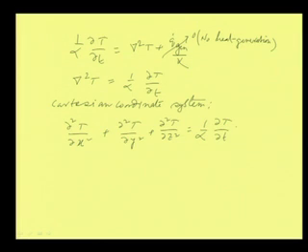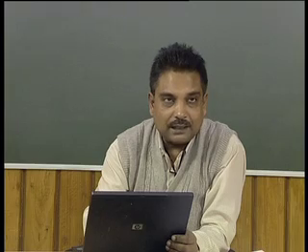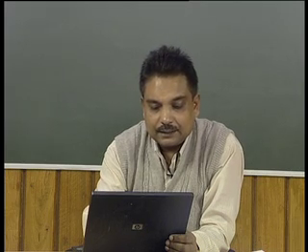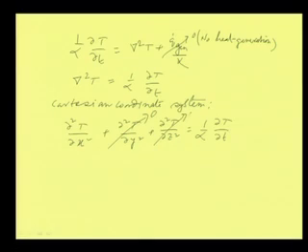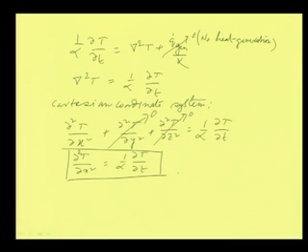We know that this is one dimensional heat transfer. We are not considering multiple dimensions, we are considering only one dimensional heat transfer, and therefore there is no temperature variation along the y and z direction. So, this equation is further reduced to del square T by del x square equal to 1 by alpha del T by del t. We have already seen that the equation can be reduced to this form for one dimensional unsteady state heat conduction without heat generation. This becomes the equation.